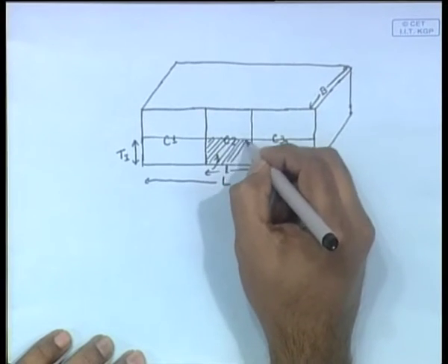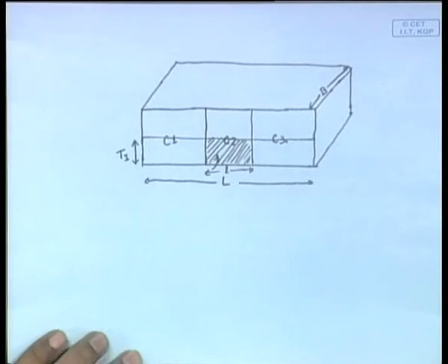Now, you will see that due to this water entering, buoyancy is lost, right. But remember the weight of the ship, let me explain. First of all, there is the ship itself, with its components, and it has a particular weight. Now, water enters. So it is the weight of the ship plus the weight of the water that is the total weight acting down.